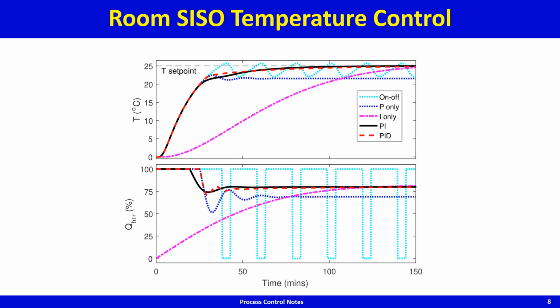And then you switch on the heater, or you switch on the controller, and you could have on-off control, proportional control, integral only control, proportional integral control, or PID control. What's plotted in the figure are responses for the different types of control algorithms. With on-off control, as you switch on the controller, heater duty goes to maximum and stays there.